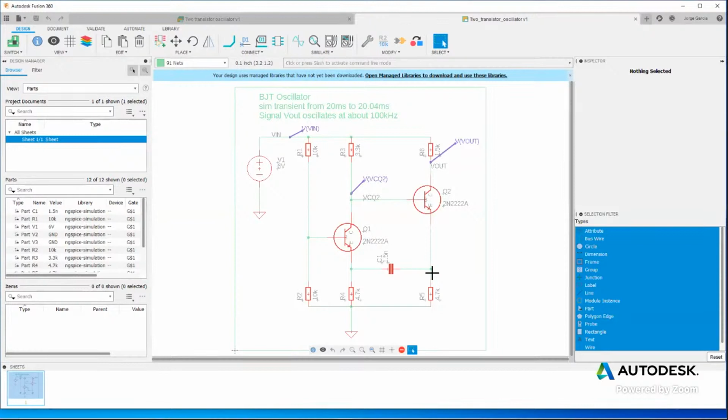So this voltage starts to rise, rise, rise, and because the capacitor resists that change, this node is going to eventually creep up also. If it creeps up enough, it's going to turn this transistor off. When this transistor turns off, all the current that was going through it now goes through this transistor, and this one gets driven even harder.